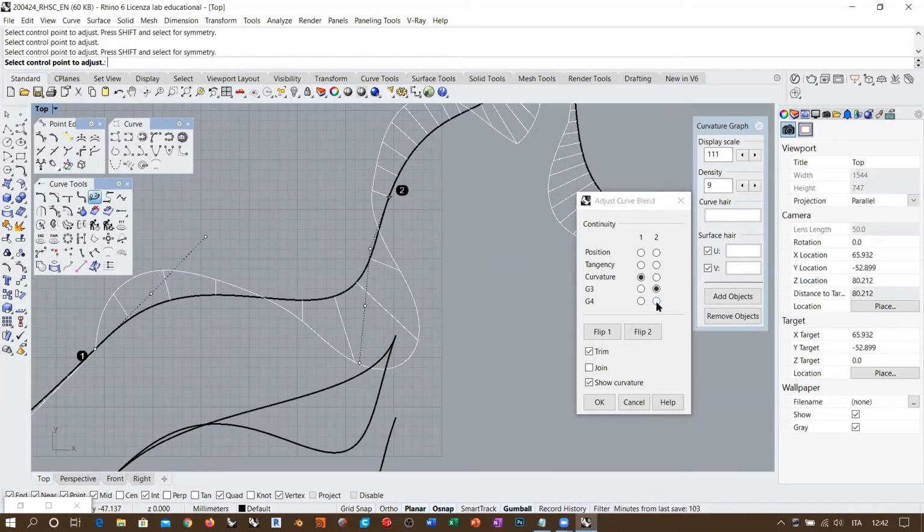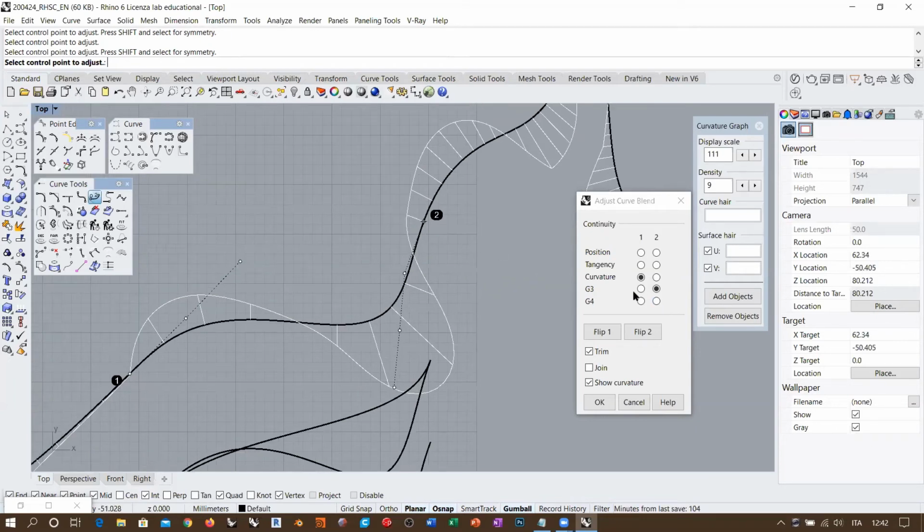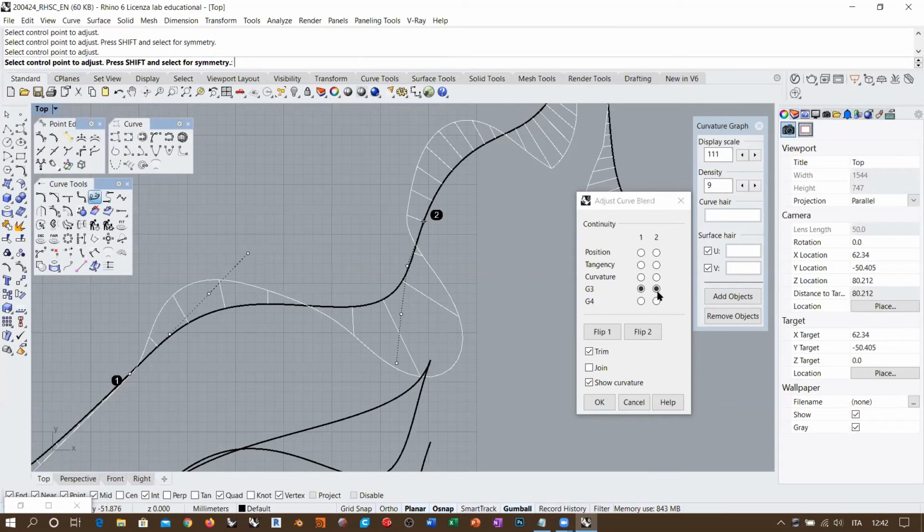But that's why, for example, I also wrote in the book that discontinuities higher than the pop or crack are also difficult to imagine with a geometrical representation. So they are not even taken into account. You can go as deep as G4 if you want, but it has a very specific meaning that normally you don't take into account in a normal workflow. But anyway, in this moment, you also got an explanation of the G3 continuity.